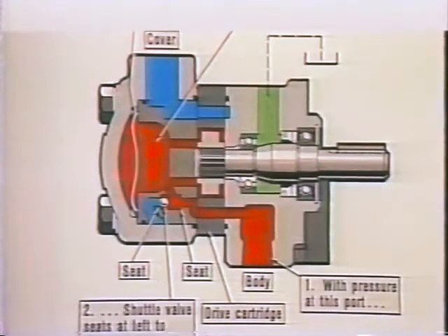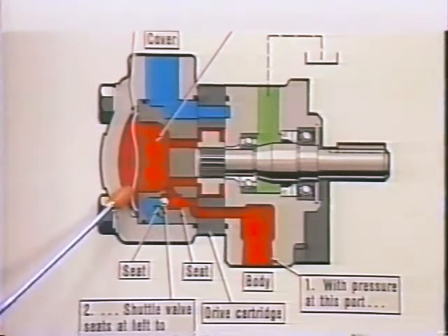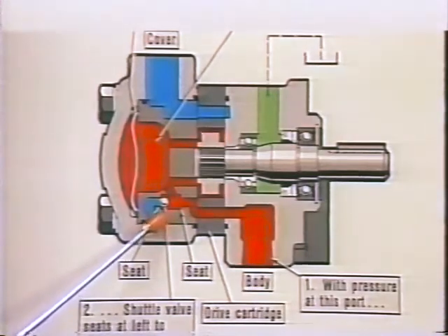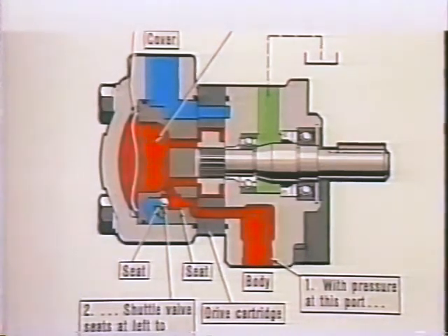This is another view of the rocker arm motor. It has a spring-loaded pressure plate. Oil, under pressure, coming in at the bottom port through a shuttle valve in the pressure plate, allows us to pressurize the plate. This gives us the force we need to close up the running clearances.